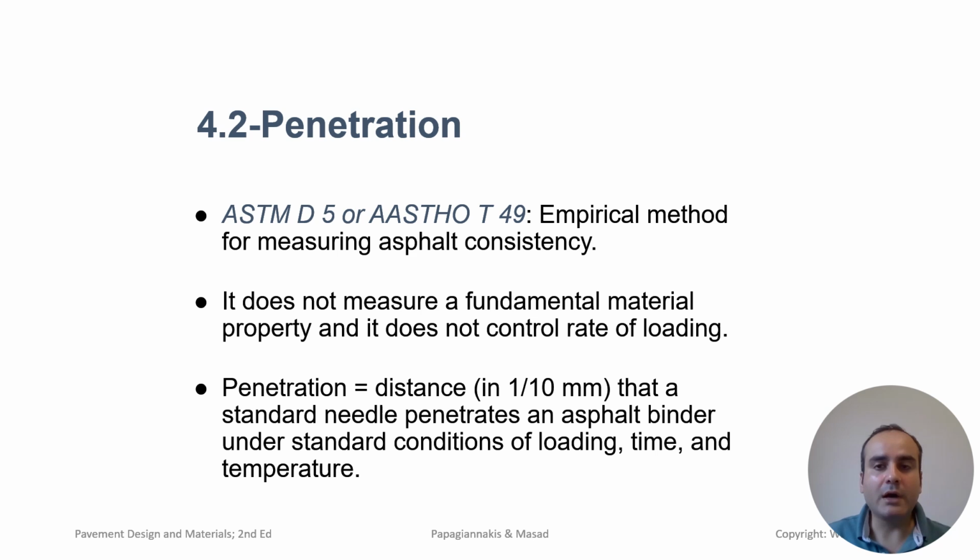A softer binder or a higher penetration value allows for more flexibility, which is useful in colder climates to prevent cracking. A harder binder or lower penetration value provides more resistance to deformation, which is useful in warmer climate conditions to